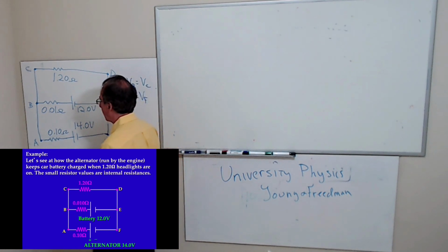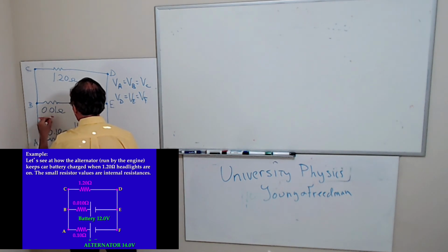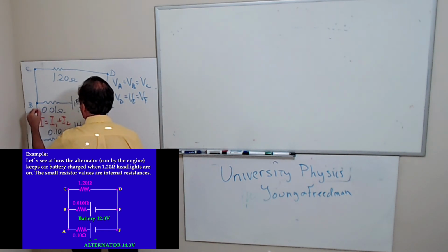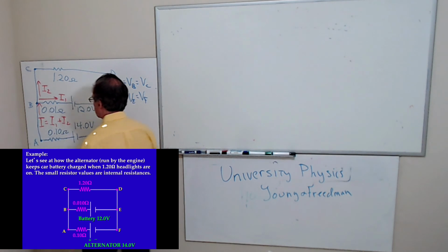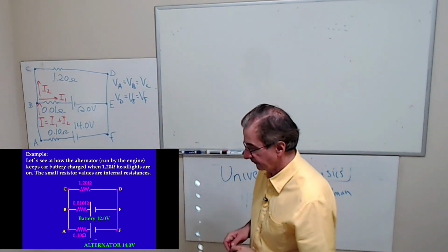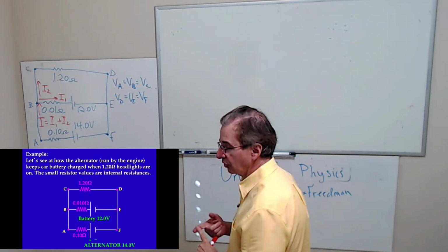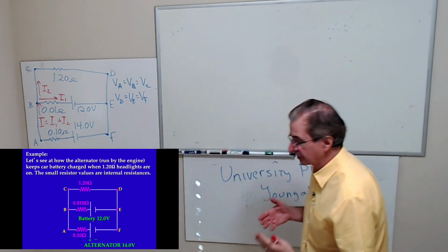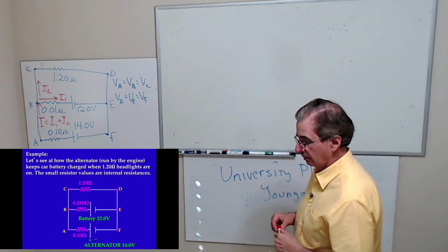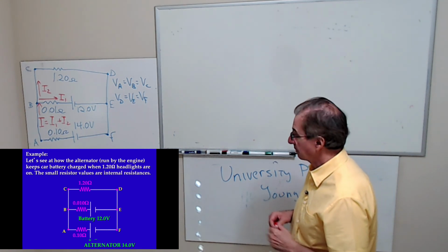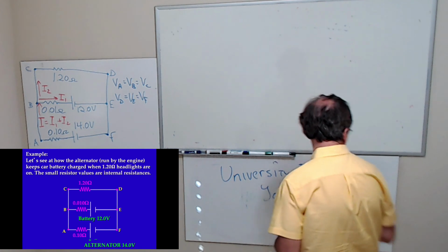So I'm going to choose currents. I'm going to apply Kirchhoff's current rule right here at this junction. I'm going to have a current equal to I1 plus I2 going right here. I1 goes this way, and I2 goes this way. So by drawing that, I see that I depends on I1 and I2, and I1 and I2 are independent of each other. So that means I have two independent currents, so I have two loops I have to write. I've got to write two sets of equations.